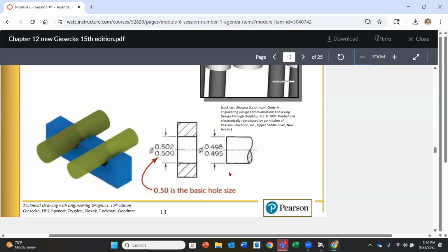They do. They actually do. So what happens is, and it's really the combination of what the three of you just said, those chips that are on the inside get to be bigger and chunkier, and they actually start working that hole as they try to come out.